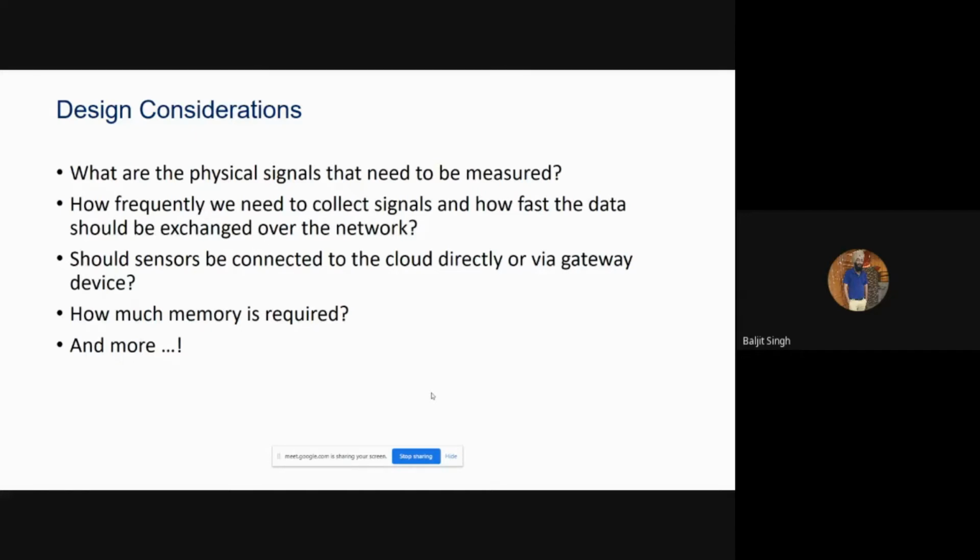Okay, so these edge devices can be connected through offline communication like Bluetooth, Zigbee or radio frequency RF, and the data from all these microcontrollers, all these edge devices, can be collected at a single control unit, which we term as a gateway.